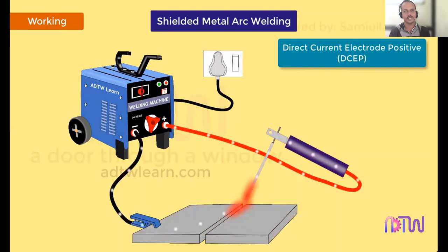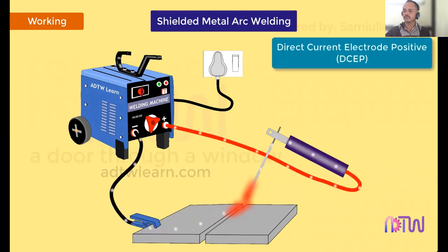However, when the electrons flow fast from the workpiece, the dirt and oxide layer is disrupted, also known as arc cleaning action, thus helping in producing a quality weld product. But it gives lower strength welding as compared to the other type. After setting the necessary current and voltage, another type.